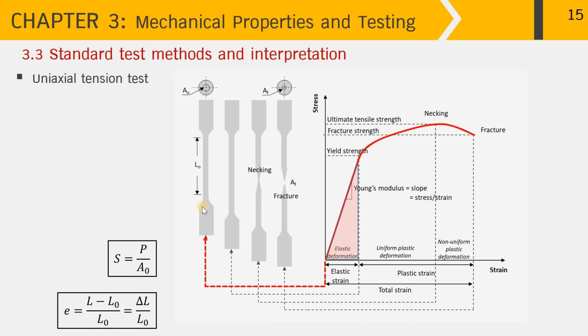For a summary, we start from the specimen prior to the test with the original dimensions of L0 and A0. Then, once it extends to the elastic limit, the specimen extends along the gauge length uniformly, and beyond the elastic limit, yielding continues till reaching the maximum point where the specimen bears the highest stress level. Beyond this, necking takes place, and the deformation is not uniform anymore. It is confined in the necking area till reaching the fracture stage over here. Right, this is how a specimen experiences tensile loading till fracture.